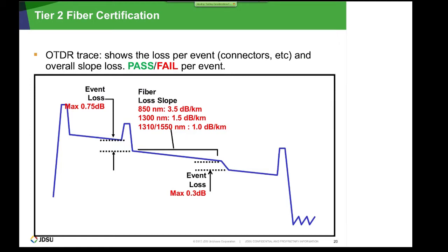How should the fiber be certified? You should use not only a laser source and power meter to measure insertion loss. You should also perform OTDR measurements. Why? OTDR measurements also perform reflectance detection as well as calculation of optical return loss.